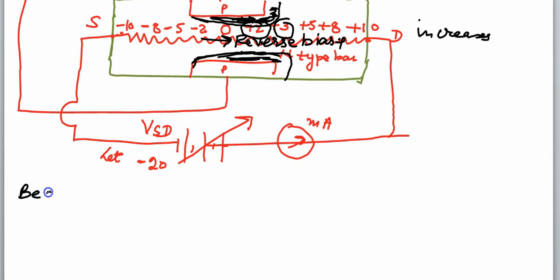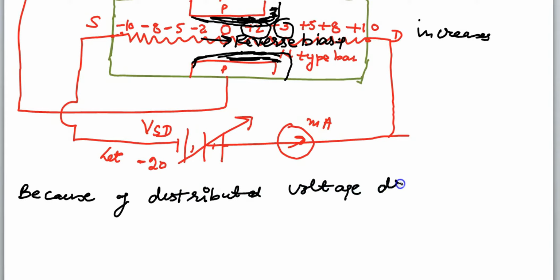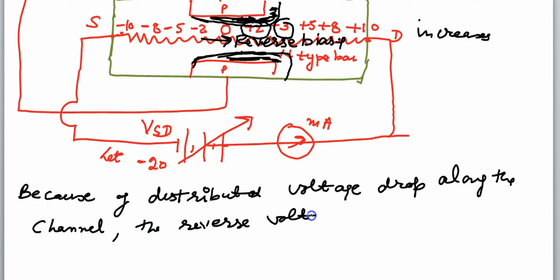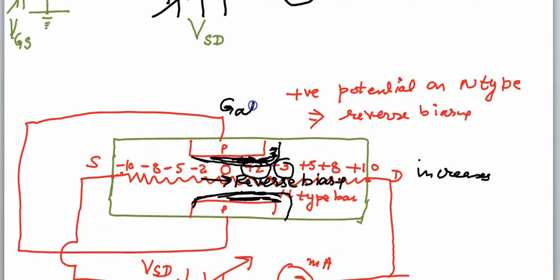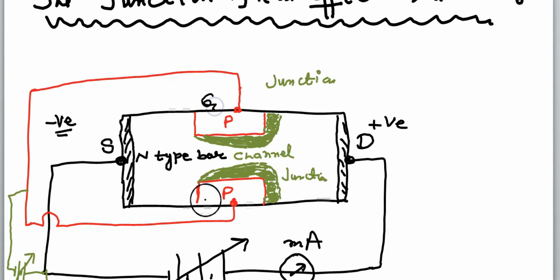It is wedge shaped like this. And remember, the gate can be open or closed, and current has to cross through the gate. If the gate is given a negative potential, it will become closed. It will become more closed, and the current will decrease. If the gate is at less negative potential, the gate will be somewhat open and there will be more current.